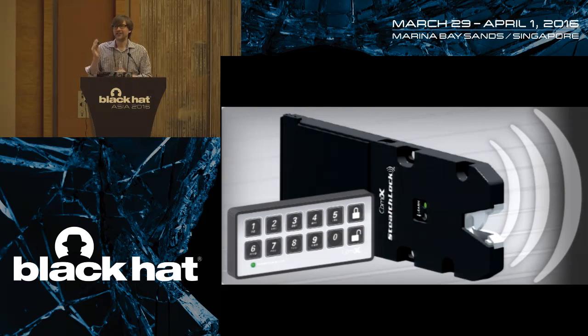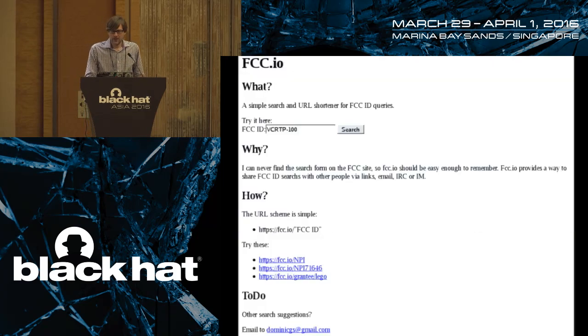When you put the battery in, it doesn't immediately transmit. It doesn't transmit until you enter a PIN and then press the lock or the unlock button. So while you enter a number, which is a 4 to 8 digit number, it doesn't actually transmit. But then when you push the lock or the unlock button after entering a number, that's when it transmits. So it seemed to be pretty straightforward. When I press lock, it should be sending that PIN with a lock code. And when I press unlock, it should be sending that PIN with an unlock code. And ever since we fixed that, this device has worked just fine.